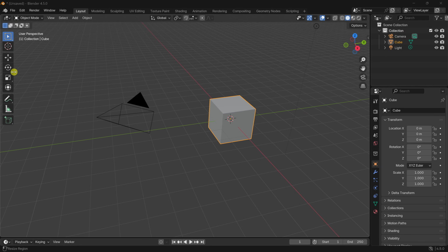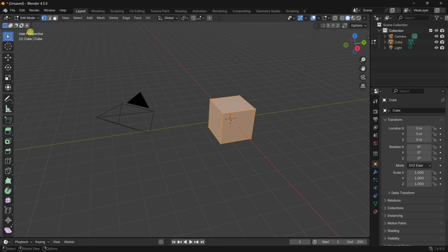The tools available change depending on the mode that you're in. Right up on top, you'll see this drop down, and we're currently in object mode. This gives you quick access to tools like move, rotate, and scale, but we could also switch into a different mode. Here, as an example, I'll click into edit mode, and you'll notice I now have many more different tools on this list. Right up on top, you can edit the vertices. Over here, you could edit an edge of an object, and over here, you could select an entire face of the object that you have in your 3D viewport.